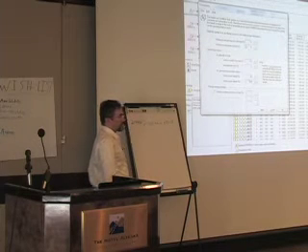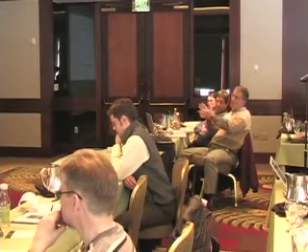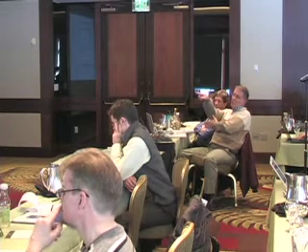So again, for simplicity's sake, let's say that the maximum primary load was 100 kW and it was operating at 100 kW. And I have high wind conditions, so 100 kW is going for the primary load, 100 kW is going to the secondary, which would be the thermal dump load. On this, should you put 50%?